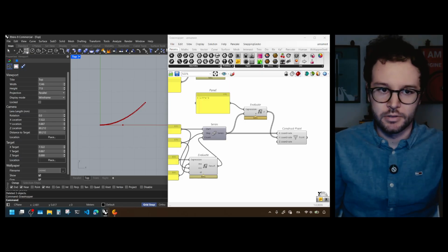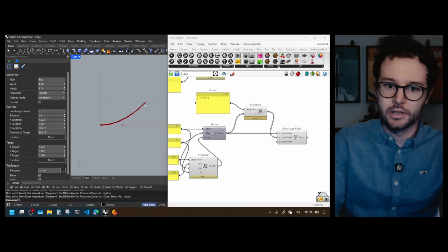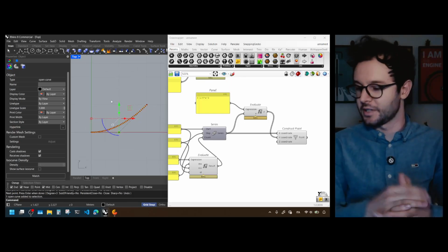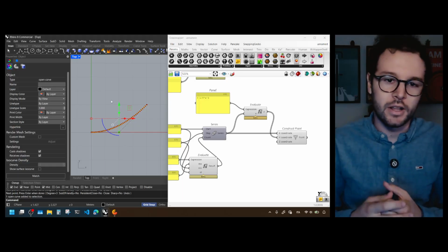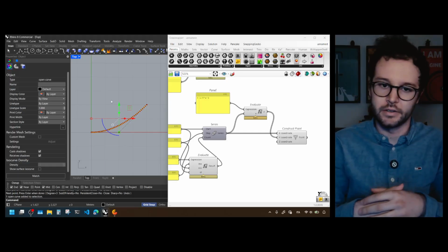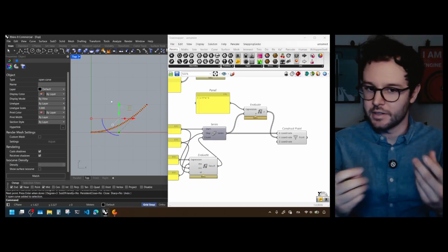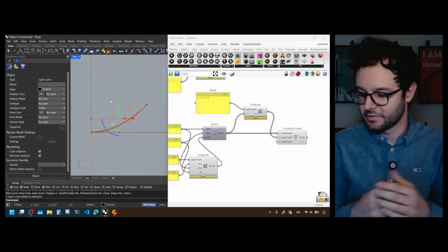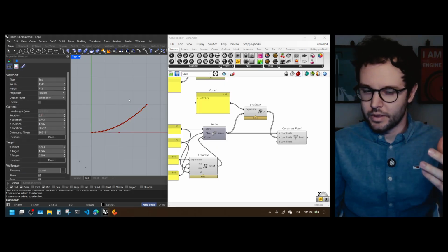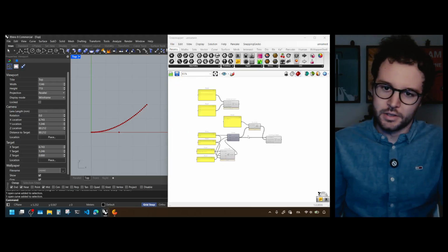Let's try to use the Rhino command for the curve and create a NURBS. And indeed, we're happy about it, because the NURBS is actually represented by a parabola. So what does this mean? Well, it means that the curves that are shown on screen when you use Rhino or any other CAD are actually just polynomial functions, cleverly tweaked so that they pass through points. Now, we made a very simple example with an explicit form of the parabola. This is not actually what the solver is doing.